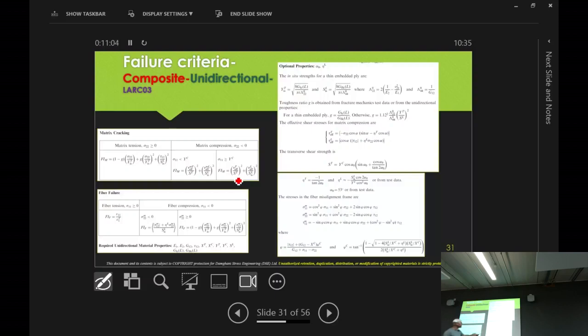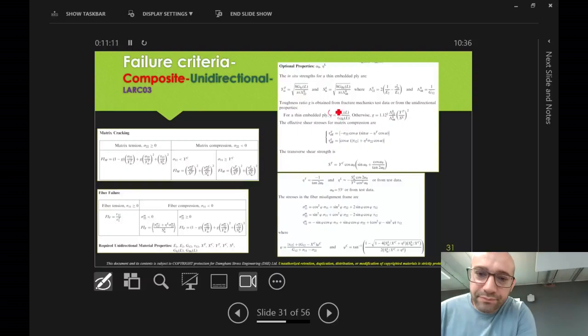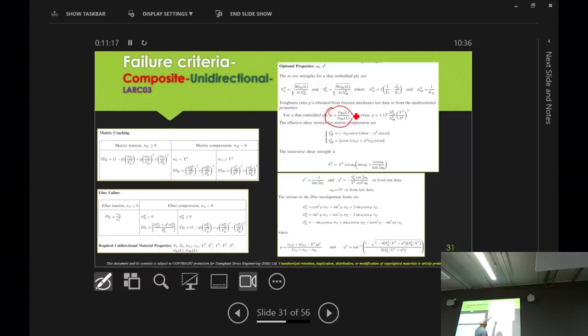because you need to know about the fracture toughness of materials. So G1C, G2C up there. So that small g is essentially the ratio of fracture toughness in mode 1 and fracture toughness in mode 2; divide them, and it will give you g. And finding G1C and G2C is quite a significant effort itself. The testing for that is quite tricky and significant. And then you've got eta, and all of these formulations, you need to know all of that. That requires a lot of testing, but it will give you a good prediction and approximation.